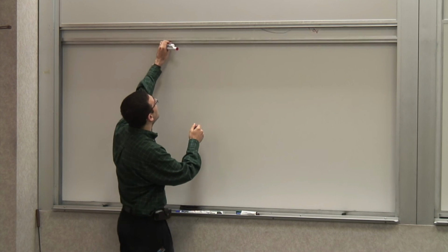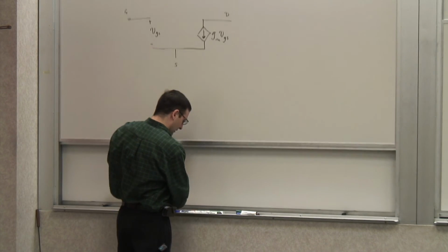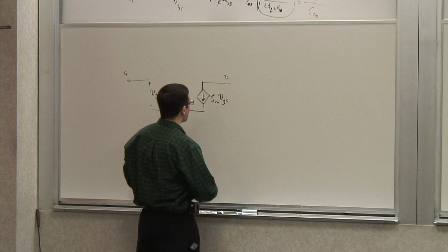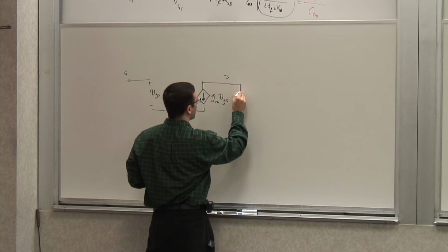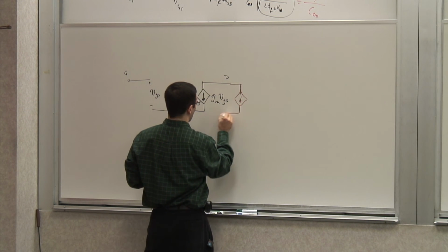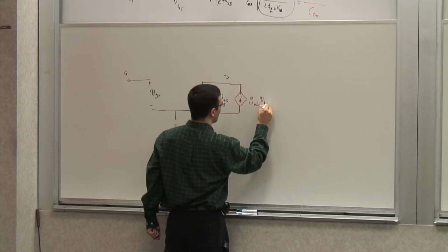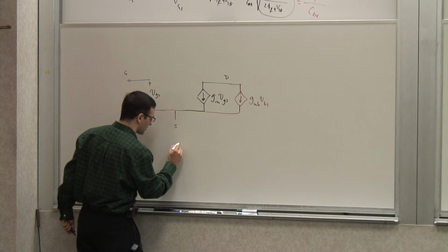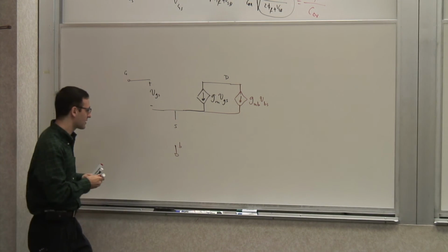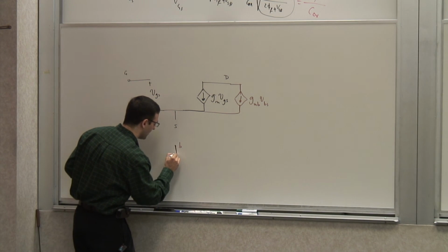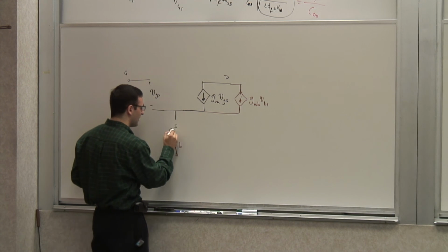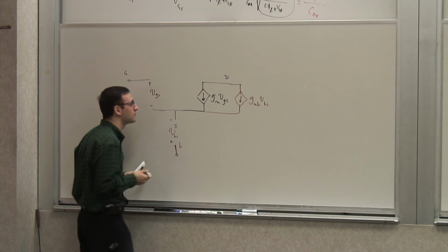And in our model for the transistor, that corresponds to a change in the drain-source voltage. So it's a GMB VBS. And VBS, this is the bulk. So this is the fourth terminal, whatever it is connected to. So whatever that terminal is, it's called bulk. So VBS is this voltage.